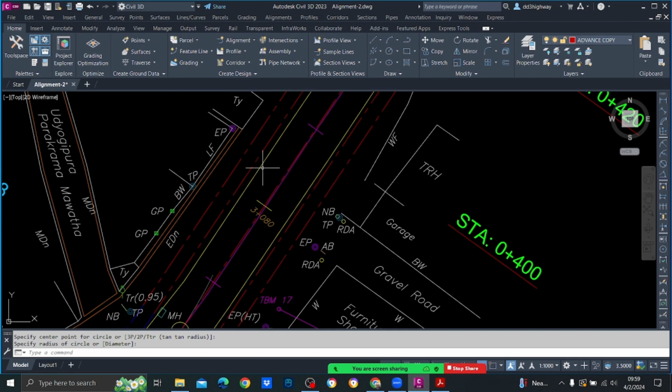So we are going to run the existing road, because you have to make sure that 100 millimeter is kept throughout the existing road only. Beyond that, there is no such requirement. Understand? You have to have the minimum 100 millimeter thickness pavement design only within the bounds of the existing road.